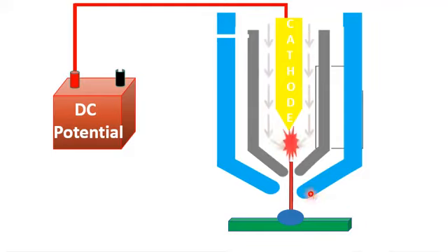So, in the cathodic arc deposition process, highly energetic plasma from the plasma arc igniter, when it interacts with the surface of the cathode material, will result in a small region of cathode material being evaporated and converted into a plasma, which is a composition of ions, electrons, as well as neutrals.